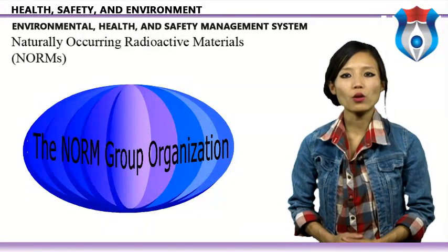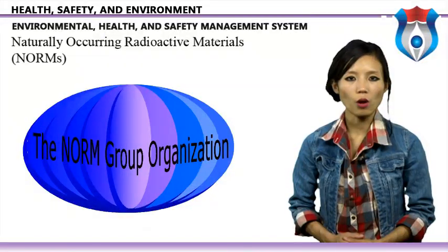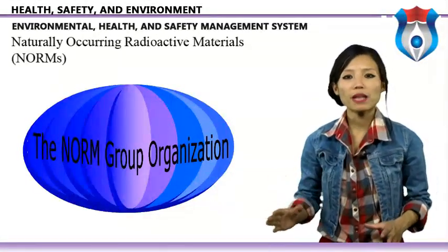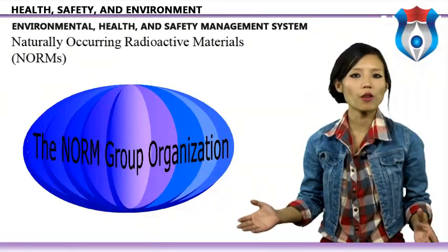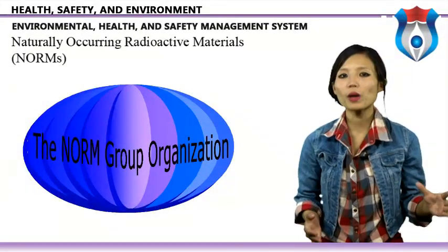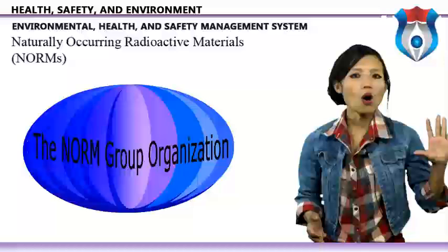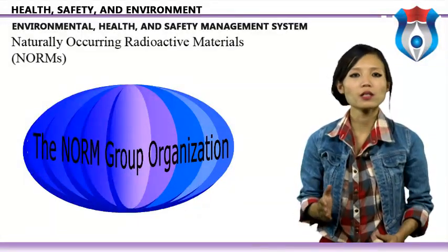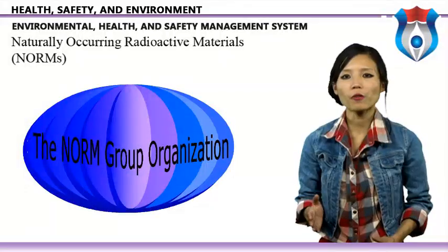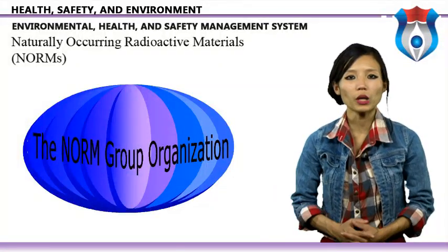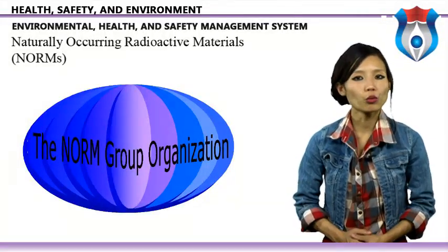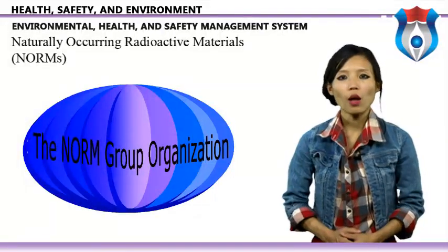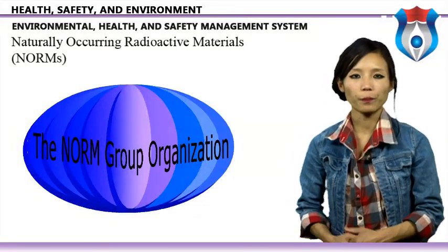Naturally occurring radioactive materials, NORM. The NORM accumulation process is very gradual and many times unpredictable. Radiation surveys of equipment and sites should be undertaken every 5 years or when equipment is to be taken out of service for maintenance. Facilities are considered impacted if surface levels are greater than 4.0 Bq/cm2 for gamma or beta radiation and 0.4 Bq/cm2 for alpha radiation.